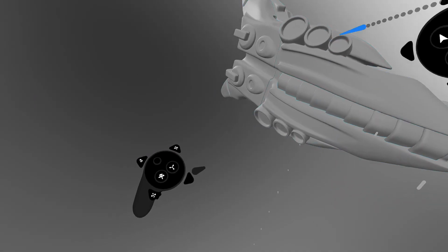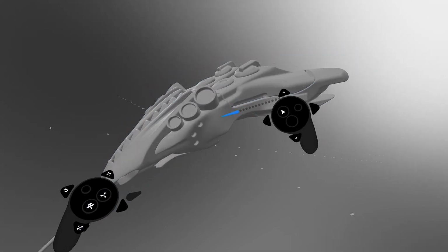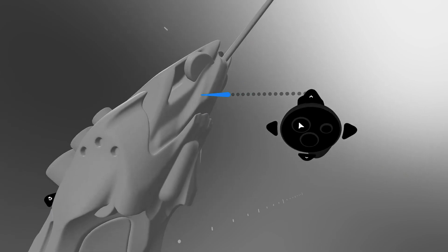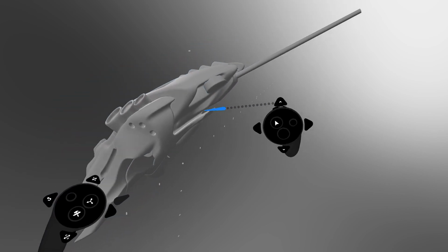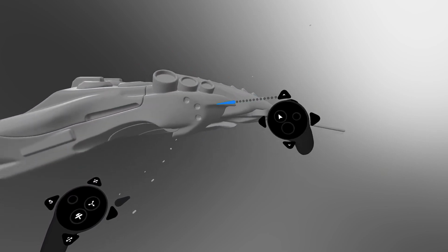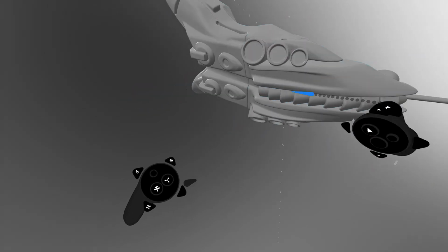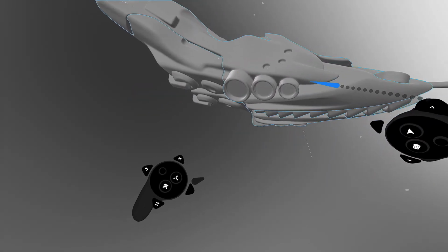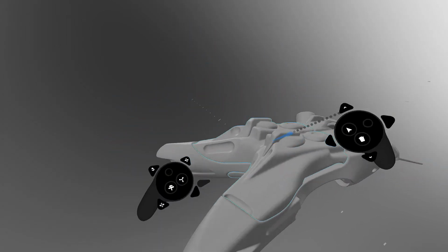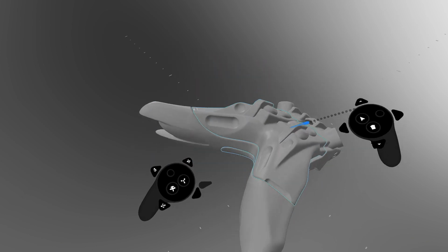And this mesh, if you do try to process it, you can pretty much retopo it real quick in Blender. Not a big deal. You could use the voxel mesh for Nanite, and you could decimate it quite extensively. But this is a real curvy surface object. It might not decimate very well. So doing a retopo would probably be the way to go, I think. It just depends on your use case, what you're creating and how you want to use it.